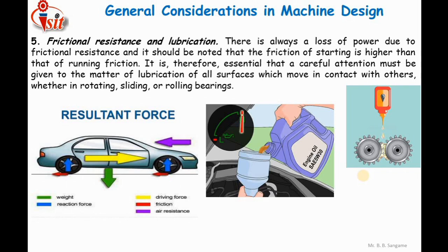Roller bearings, ball bearings are there, also many sprockets, wheels, chains, drives. So there is a lot of friction from the relative motion between all these parts. To reduce the friction we should provide proper lubrication, so that the frictional resistances can be reduced, and whatever stresses are induced in the component because of the frictional resistance can ultimately be reduced.